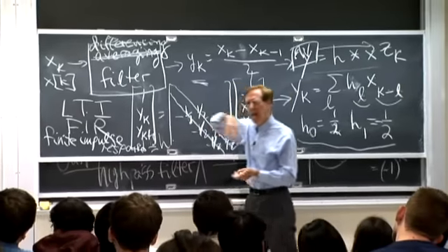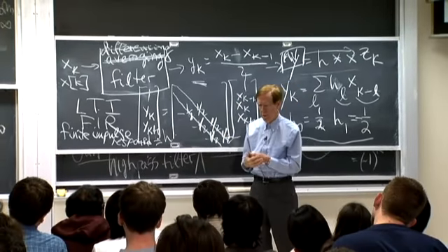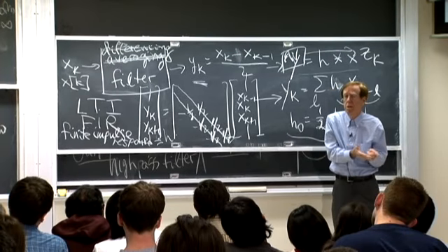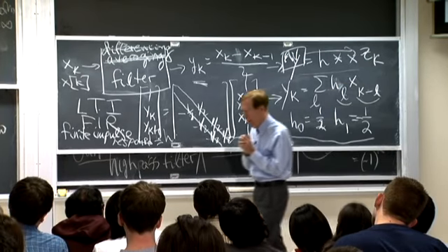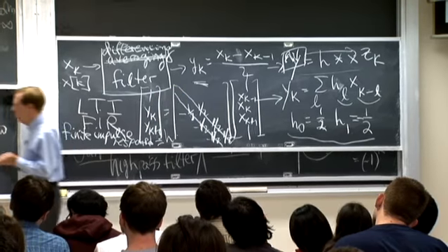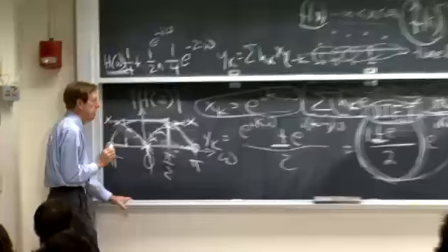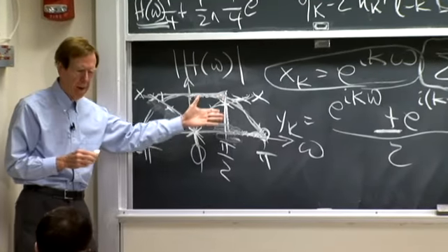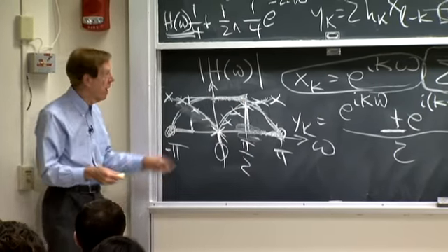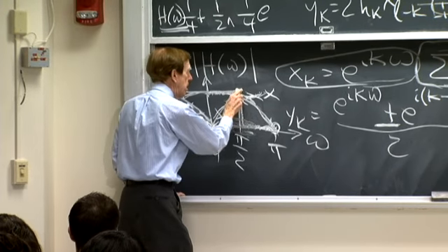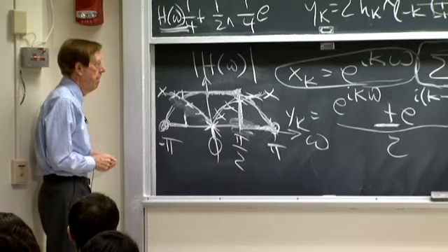Each time I did that averaging, I damped the high frequencies. So if I do it twice, I get more damping. But I lose signal, of course. Presumably there's some information in the signal in these frequencies, and I'm reducing it. And if I average twice, I'm reducing it further. So a better one would be to get a sharp cutoff.